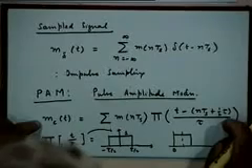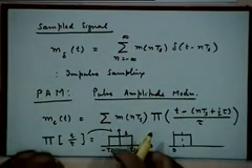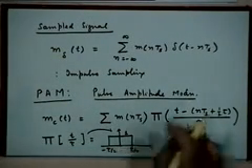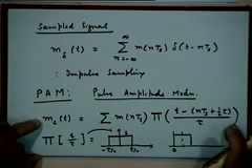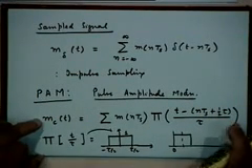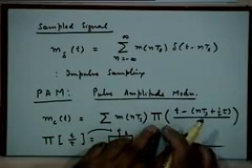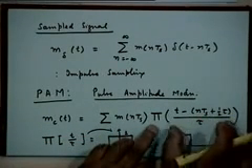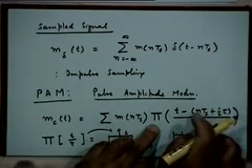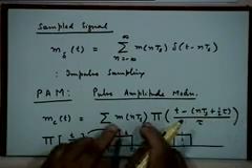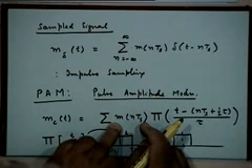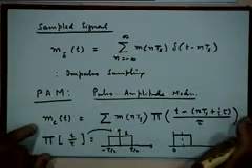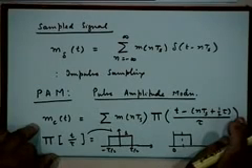Can you tell me how I can get this kind of a signal from this kind of a signal? This is your impulse sample signal, right? How can I get a PAM signal here? This is a PAM signal. As you can see, the nth pulse, which is a rectangular pulse located at time nTs, has an amplitude proportional to the message value at that time instant, right? So, this is what we call a PAM signal, right?